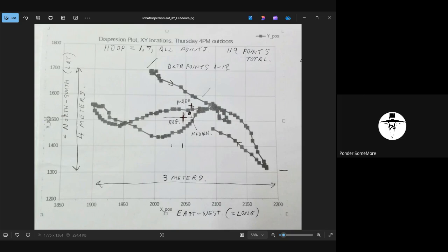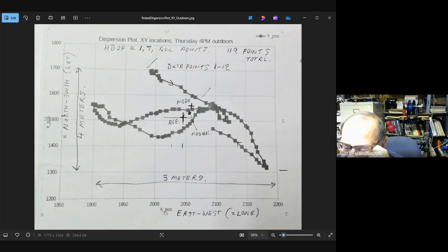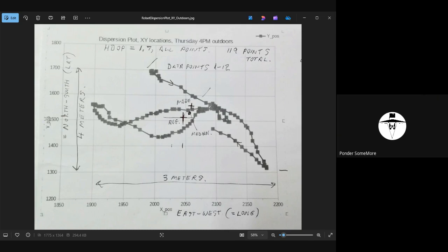Antennas are, yeah, I mean, it's worth investing in a good antenna. It's worth having a good ground plane, although the ground plane doesn't really matter. I've made mine out of a pie tin on one of my robots, and it worked just fine. The ones that ship with the F9P kits, which is an L1, L2 antenna, are thick metal plates, about 4 inches in diameter. The main reason that they're heavy metal plates is because it's magnet mount capable. The antenna is a magnetic mount, so you can also just toss it on top of your car or on top of your excavator.